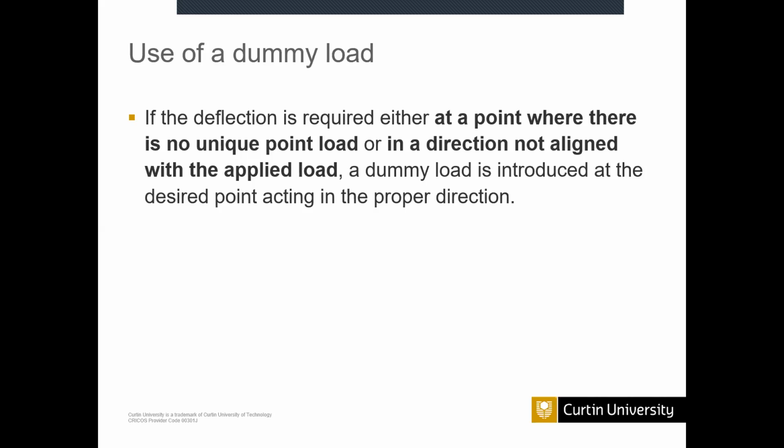So if it is deflection downward, and you have a point load upward, that is also not useful. So you need to use a dummy load downward, because even though there is an applied point load at that point upward, due to the resultant force, that particular point will deflect downward. Then you need to use a dummy load. Okay.